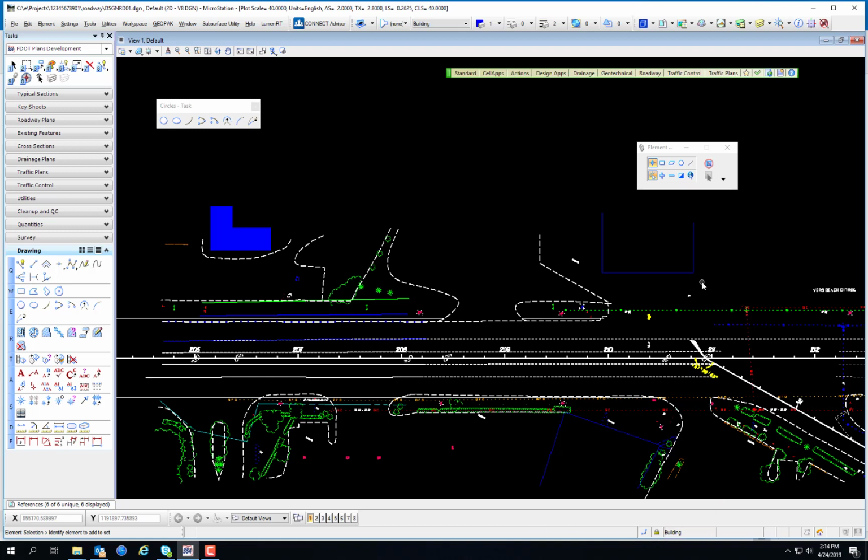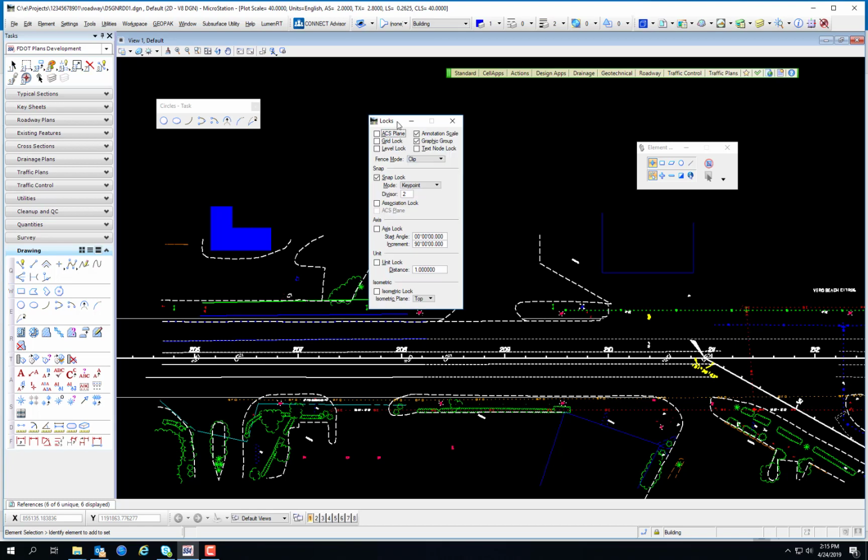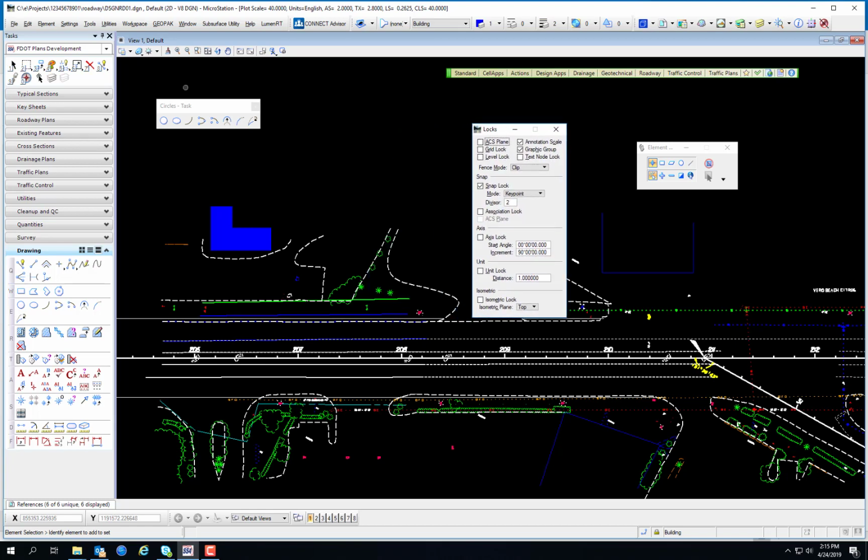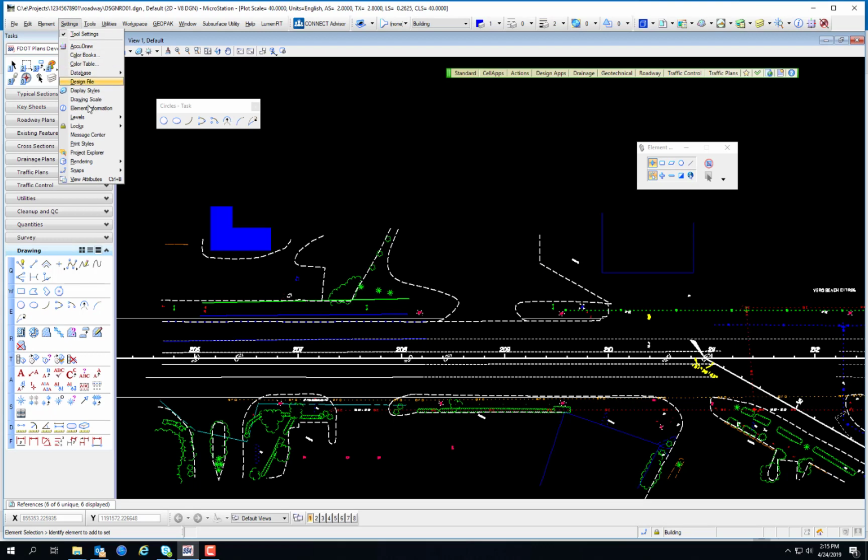The Locks dialog is used to set each of the locks and the fence selection mode. It is accessed from the MicroStation menu options, Settings, Locks, Full, or Status Bar Locks pop-up menu option, Full. Each lock is enabled by toggling on the adjacent checkbox and settings selected to affect the use of each lock. Each lock performs a different function by controlling or constraining some portion of MicroStation. There's the Locks dialog. Also, you can access it from Settings, Locks, Full.